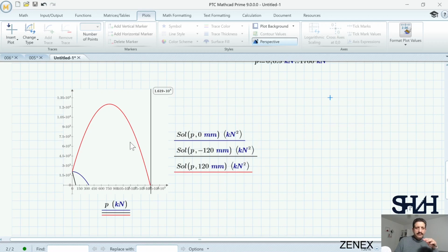And usually by default, as the load is typically coming from the top flange, it is by default the destabilizing situation, meaning that it is on the side that would destabilize the cross section when it buckles. In the software, we can adjust the setting according to our need or our task, whatever it is.